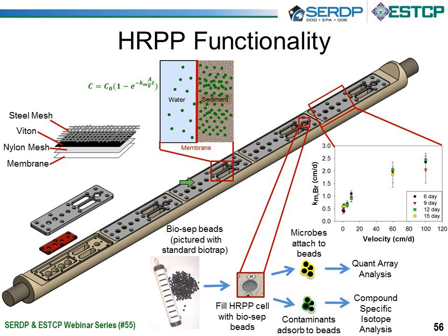There are 2 cells, duplicate cells, that are used for looking at the concentrations of any dissolved species, whether that's chlorinated solvents, electron acceptors, anything that you're interested in. And then there are 4 cells in each sample increment that are used to determine velocity based on the relationship between a mass transfer coefficient of a conservative tracer with the velocity in the porewater.